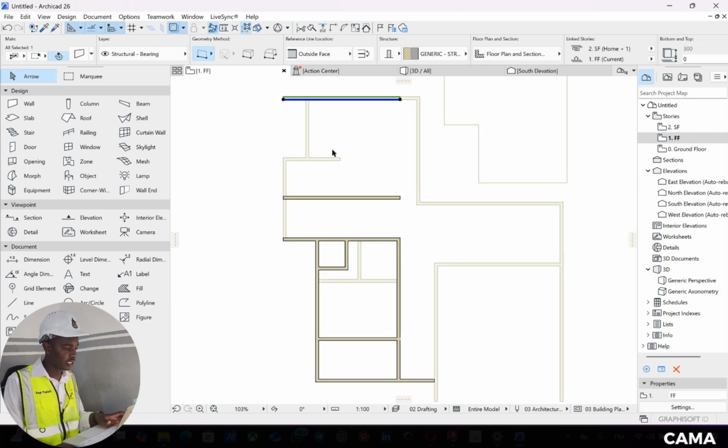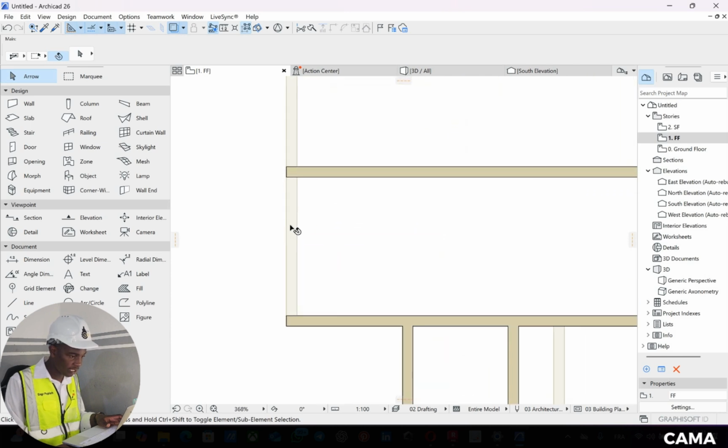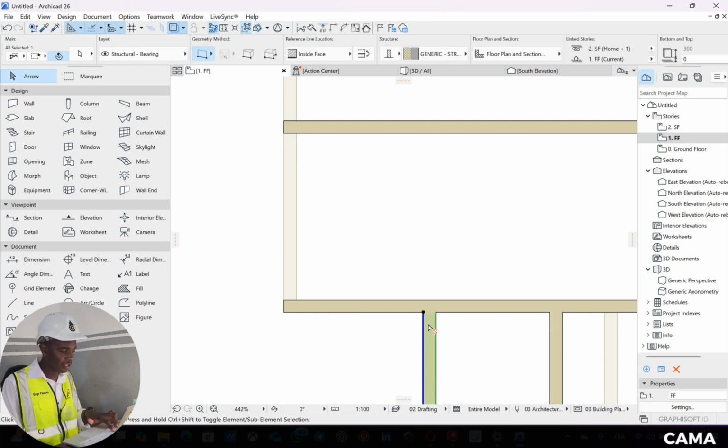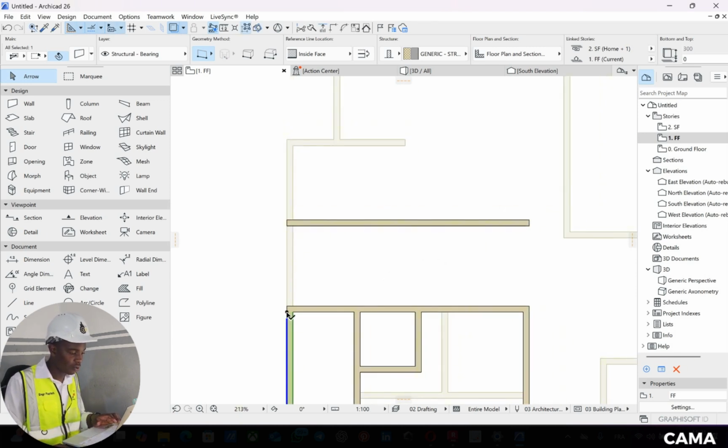Forgetting the wall thickness, you draw a wall. This wall, the wall that's placed here, as you are seeing this wall faint here, blurred here like this, is this wall. You are going to draw a wall there, but from your plans you know that this wall is placed at a distance of 150 centimeters. That is 165. You click OK.